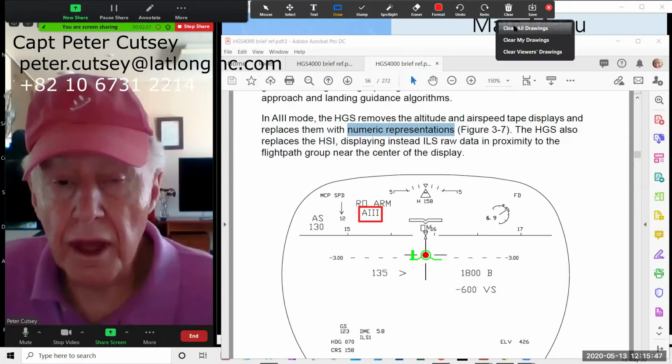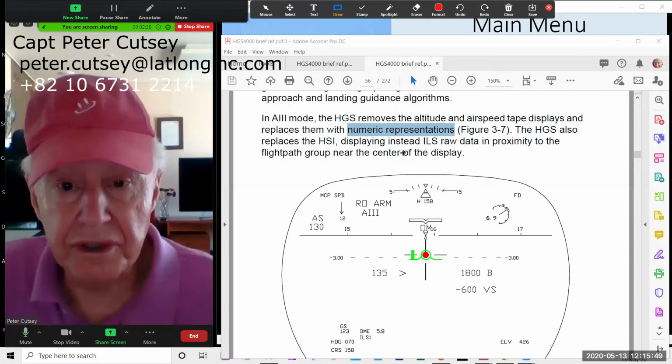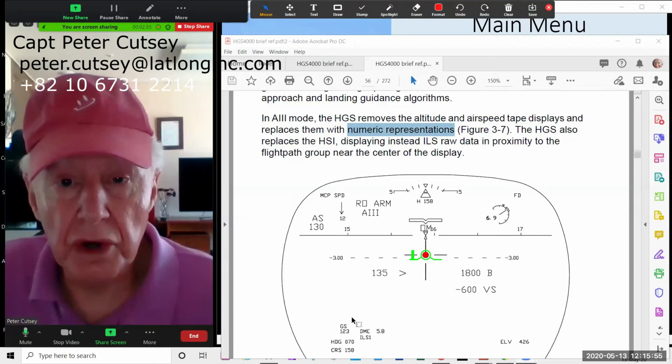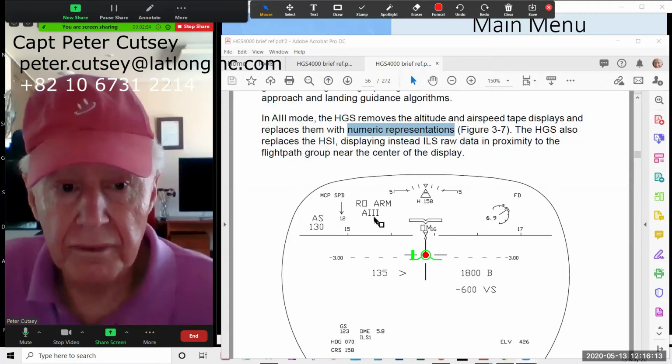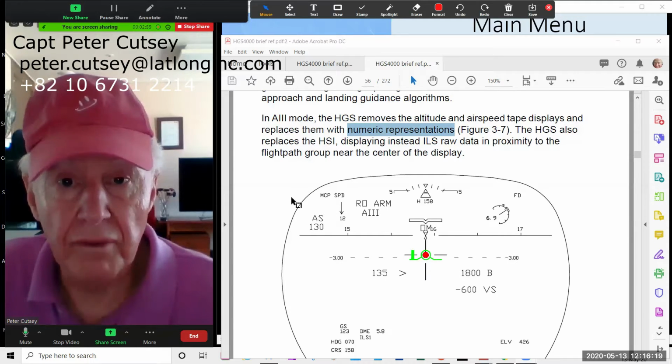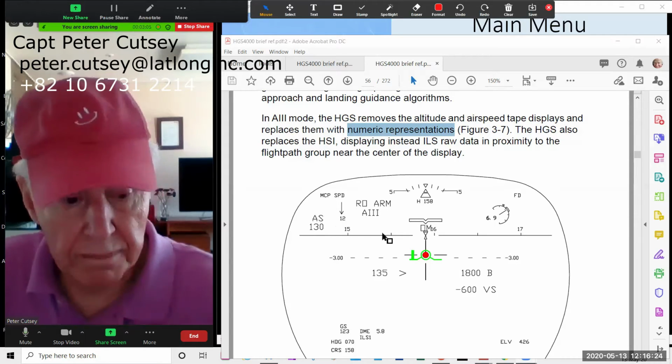The thing I teach, and I found myself in using the HUD, is that symbology is all green, and it will take a little while to get used to the green presentation. These messages or advisories don't appear to be that visible because they're all the same color, whereas with the PFD, you have a color presentation. In any case, you'll get used to it.